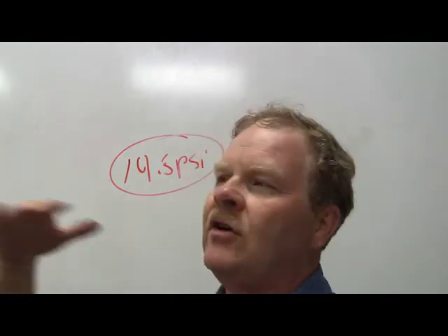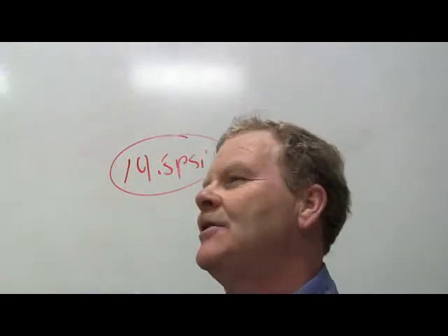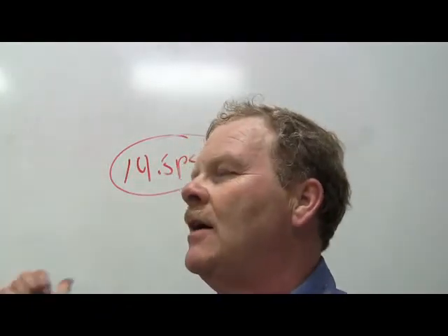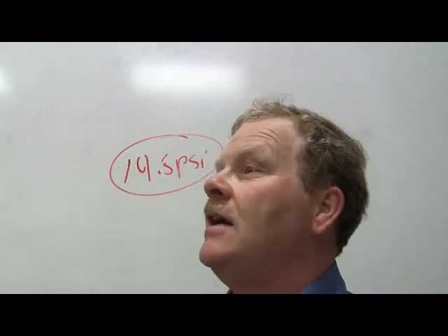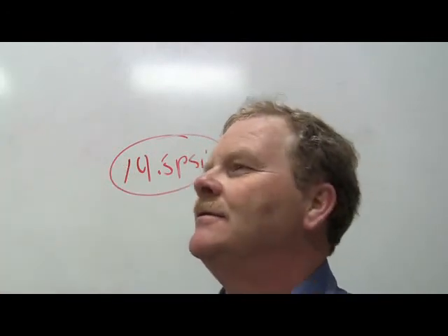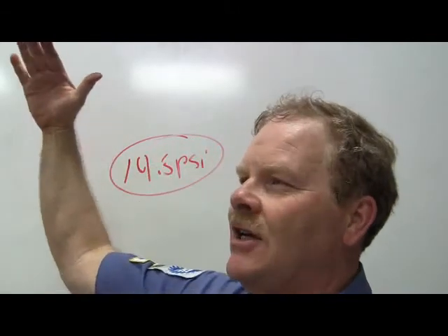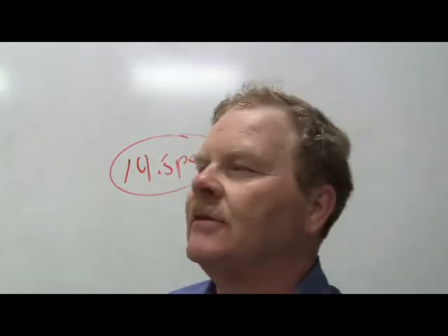If you add pressure to that, that'll be the psi-G reading. Like if you added 10 pounds to that, that would be 25 psi-G. But if you subtracted 15 from your psi-G, you'd come back to your 0 pressure. See what I'm saying?